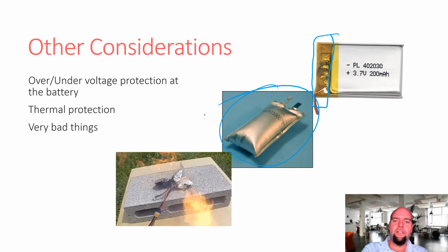They swell. If you ever see a LiPo battery that has its pack swollen, don't use it. It usually means it's gone bad. If it's swollen a lot, if it has a little bit of wrinkle to it, yeah, it might be okay. If it ever looks like that in the picture, just throw that thing away.